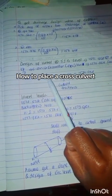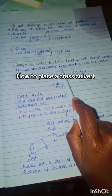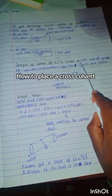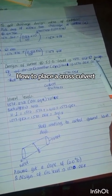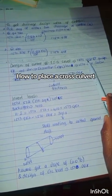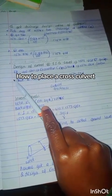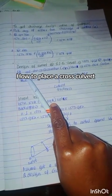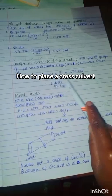The next thing to learn is the design of the culvert at GSG level. It's 1571.468 at the chainage of 9 plus 690, where this is the value here. At a distance of 6.5 meters, from the width of 13 meters over 2, we need to calculate the excavation level needed.